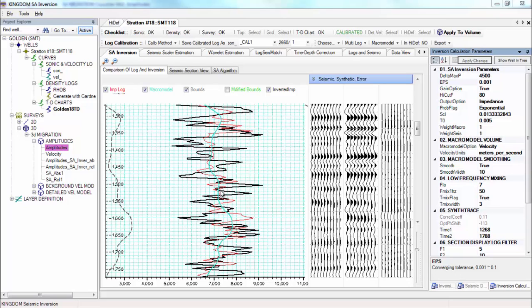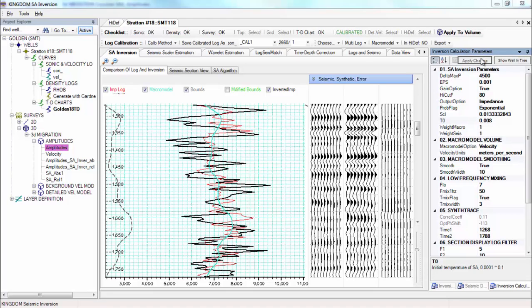I can test if injecting some more energy into the annealing helps, so I'll bump up the initial parameter T0. I'll go from 0.05 to, let's say, 0.08. There's a small improvement, and runtime isn't noticeably increased, so I'll keep that value.